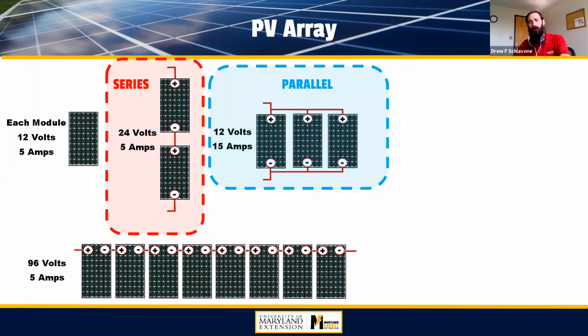Now, I'll say a little bit here about the way these can be connected. The example I just gave you was connecting in series. If you connect in series, from the positive to negative terminal of each module, you're going to sum the voltage up. Now, if you are stringing it together for other applications, you may want to keep that voltage low. There's other reasons to do that as well.